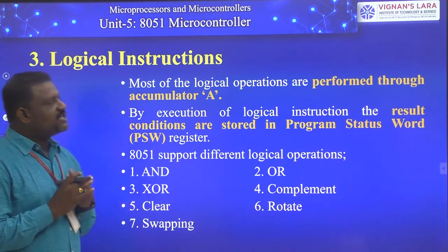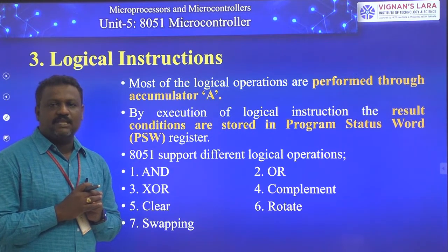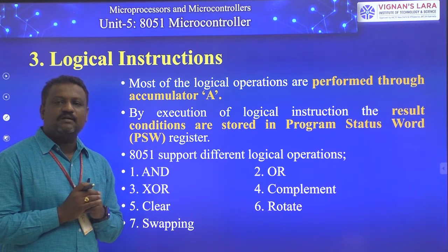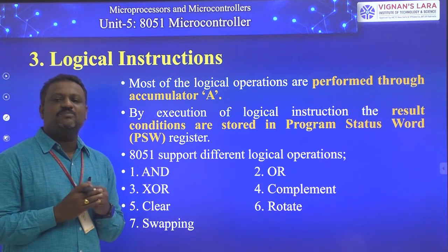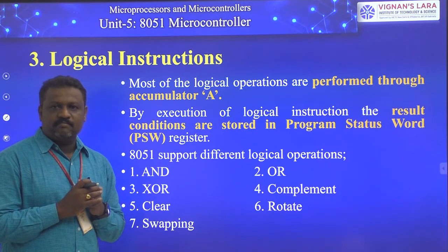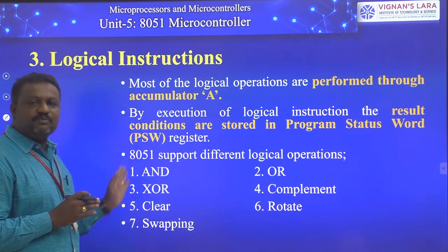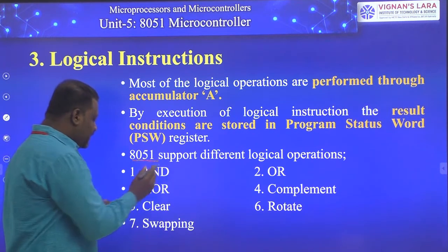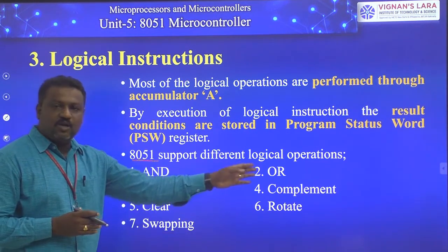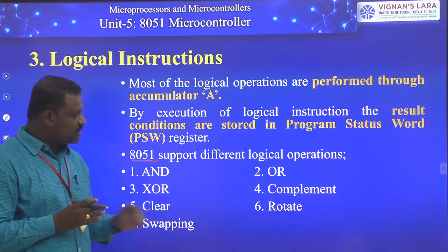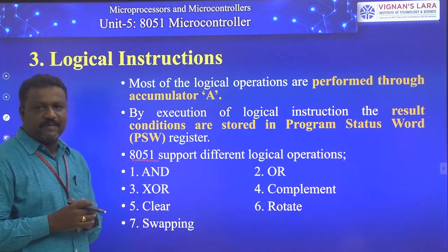Most logical operations are performed through the accumulator register A. In the 8051 microcontroller, most of your logical operations are performed through our primary accumulator register A. If you consider the different logical operations supported by the 8051, it supports 7 different logical operations: logical AND, logical OR, logical XOR, complement, clear, rotate and swap.